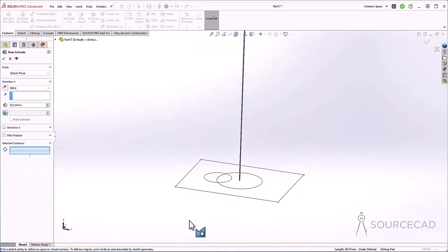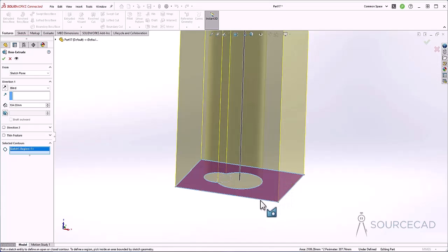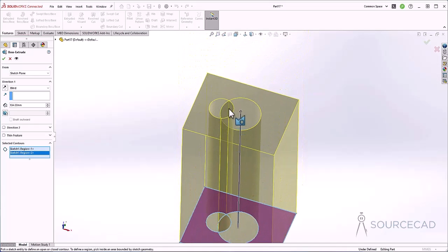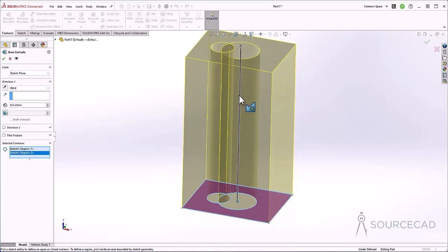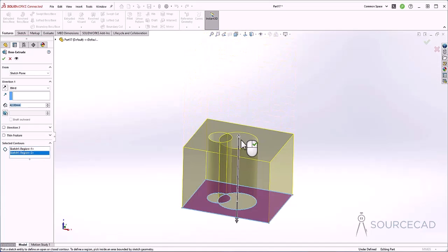Done. Now with that selection cleared, you'll notice that we have the option of selecting the boundaries. So I'll select this one, and maybe I'll just select this region. So now we'll end up with two extrusions, the one outside and this. We are not going to get these two extrusions. Of course, you can set the height as well. So you can move it using this arrow. You can drag the height, or you can also add the height value precisely here.